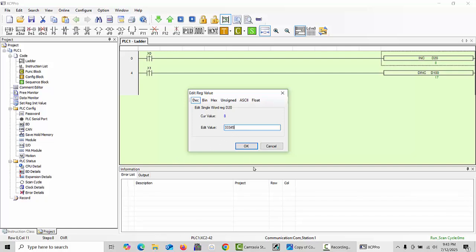33,034, a value like that, after clicking enter you can see there are red words as hints, and it says please check input range, that the INC command supports only minus 32,768 up to 32,767. If I put a value like this, it will not be accepted because I am giving a random value.